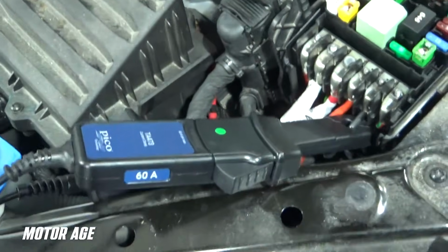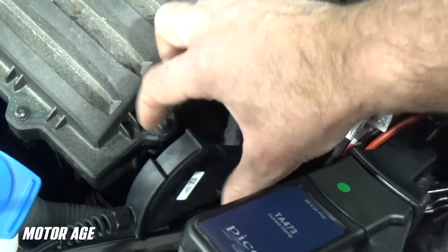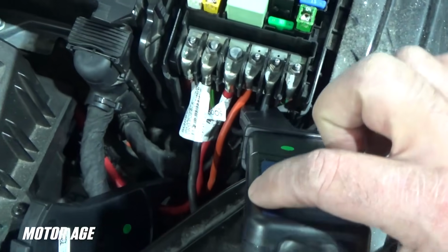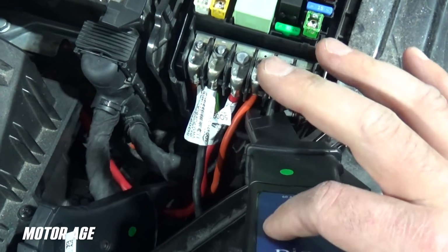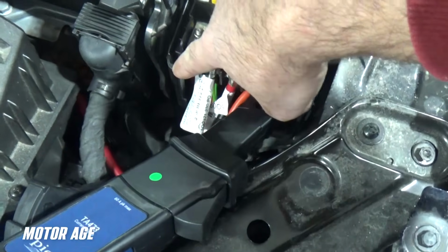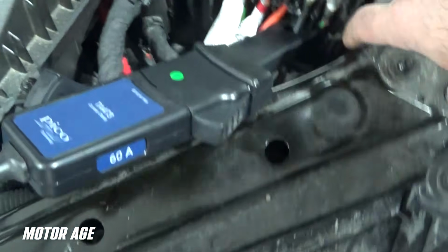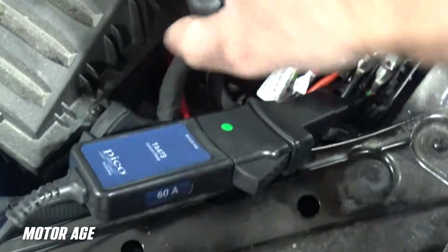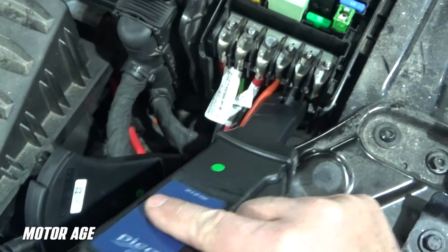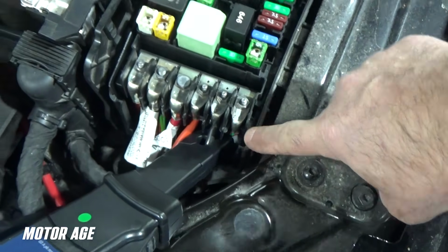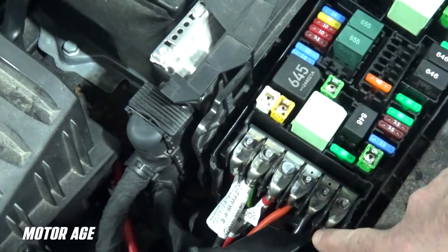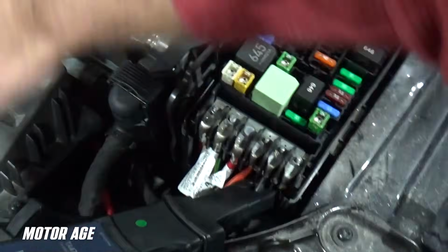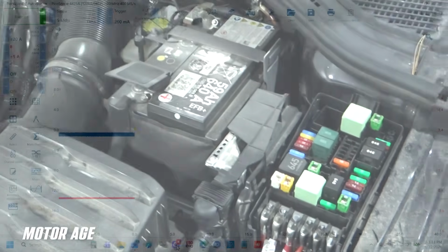And we're simply going to capture the data. What I want to see is when this amp probe shows current flow, will this amp probe show current flow or not? If the answer is no, we relocate this to a different one of these wires until we find the one that shows the current flow. So we're going to leverage this one as a trigger, an indicator that a problem is present. And we're going to leverage this one to say, is the problem present in the wire we're referencing? And if not, we move it till we find the wire that does house the problem. Again, breaking this down into 5 easy to follow sections rather than tackling the whole car at once.